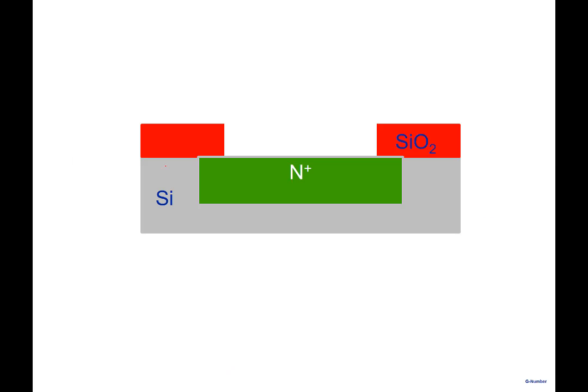So the mask cost. If you realize, what we are making is a CMOS IC, and a CMOS IC is made up of transistors, obviously N-type transistors and P-type transistors. If you recall, if I can just sketch a simple transistor here, the NMOS has N plus regions. There's an oxide here. There may be a metal, polysilicon here, and contacts and all that. So you see that the MOSFET is here.